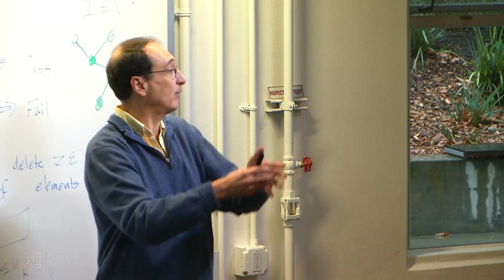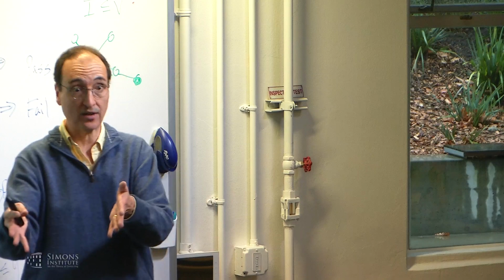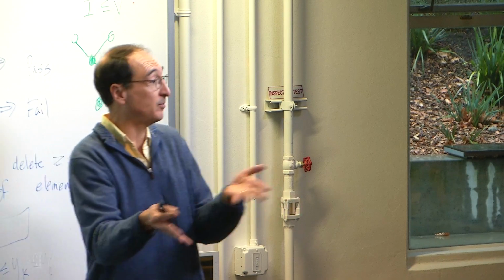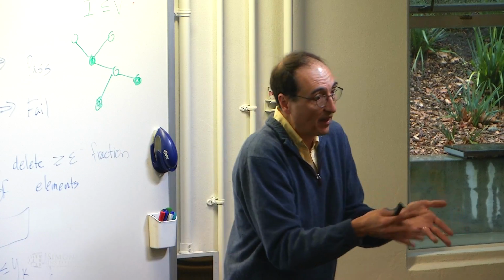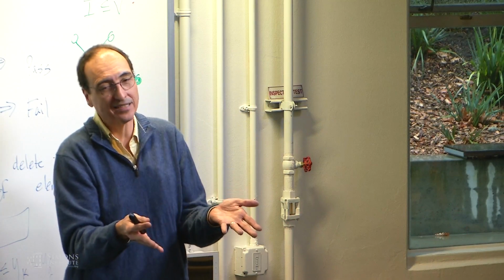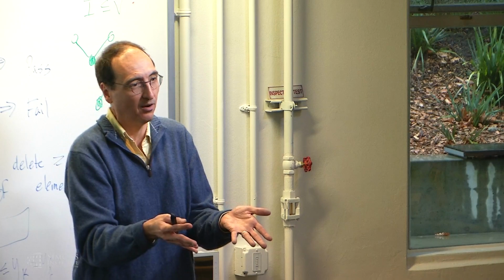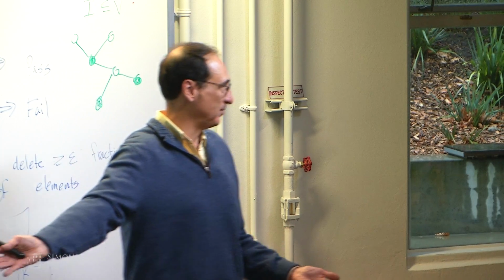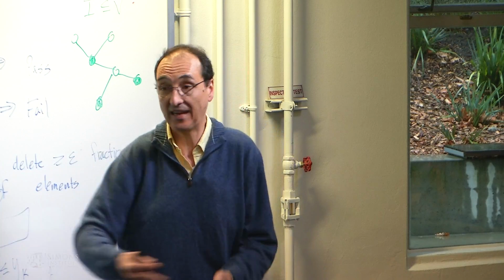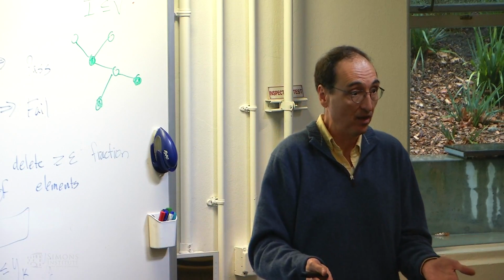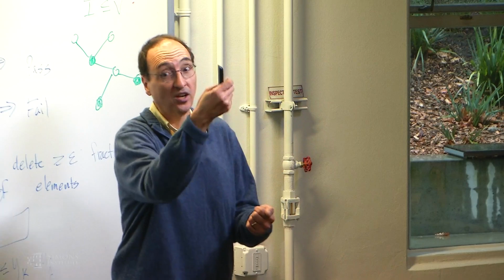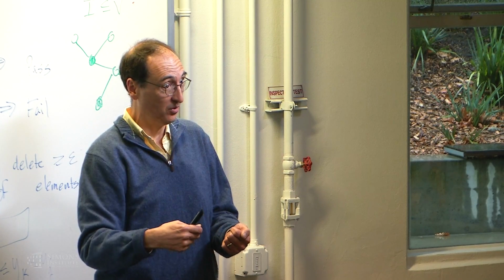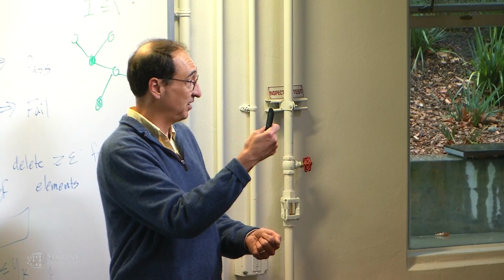Because now I know that I will stay within 10 centimeters of whatever trajectory you give me, so I can use that for my planning purposes. Right? Because I need to know that you might be up to 10 centimeters off. On the other hand, that lower layer has to say, look, I can't stay within 10 centimeters if you tell me to turn really sharply at 20 miles an hour and you want me to go around a really sharp turn. I can't do that. I mean, just physically can't do that. So I have to assume that you're going to give me, right, reasonable trajectories. And under the assumption that you give me reasonable trajectories, I'll guarantee I'll fall in within 10 centimeters.